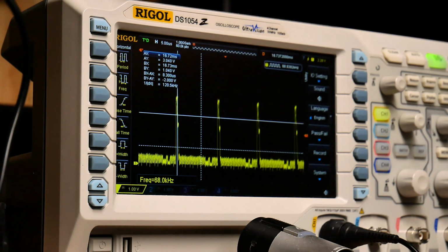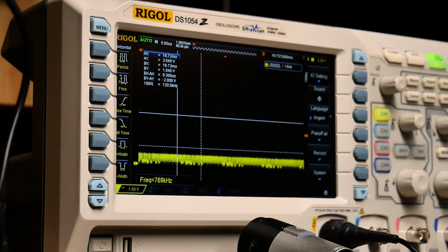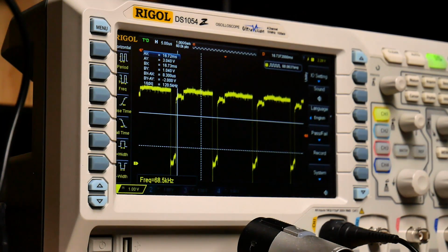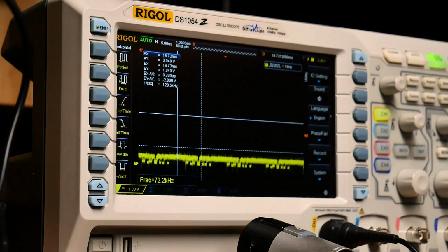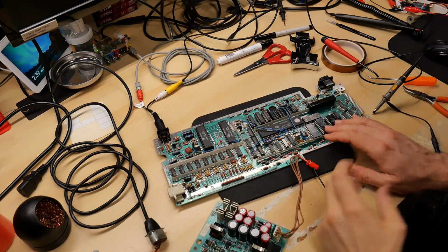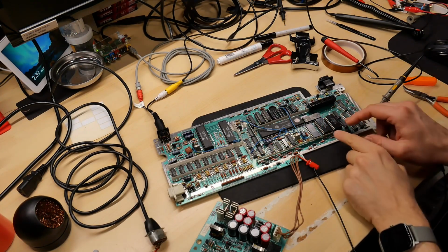Something is wrong there. Pin 2, which was fine, looks screwed up still. 3 was okay before, and it is still. That one's bad. Bad. And that's bad. And that's bad. Okay, so it looks like the problem didn't really move with the two chips. So swapping those kind of confirms that the RAM chips are probably okay.